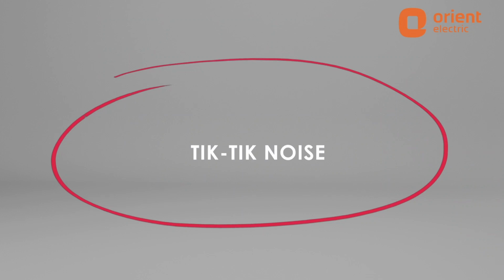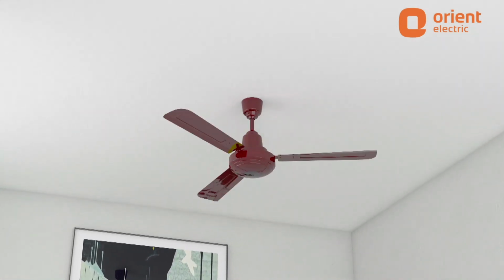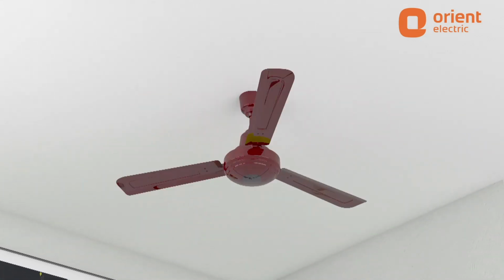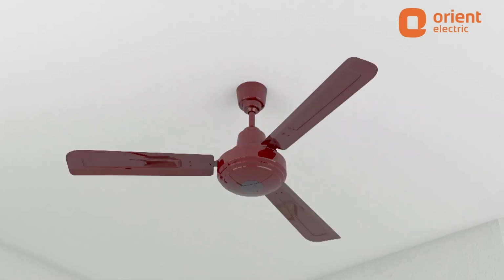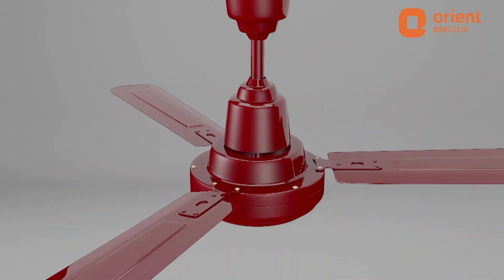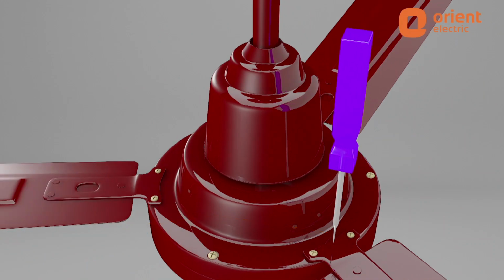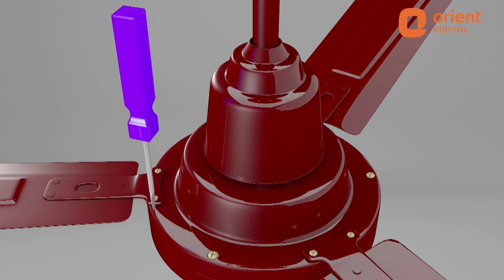Tick-tick noise. A ceiling fan sometimes starts making continuous tick-tick sound, and this is generally caused by loose blade assembly screws or loose trim fixing screws. If that is the case, you should tighten the screws properly. If the problem is loose blade and shank assembly rivets, you will have to replace the blade.